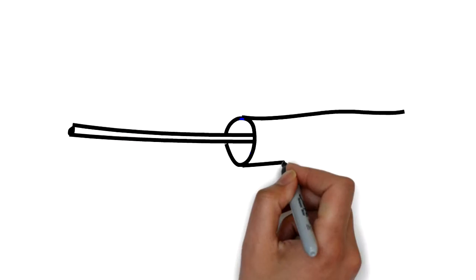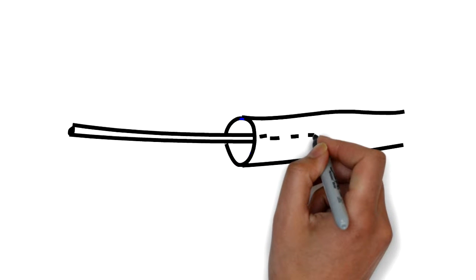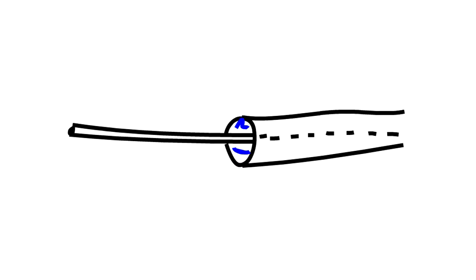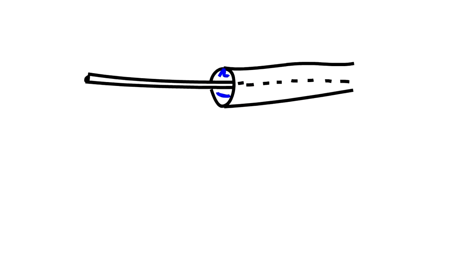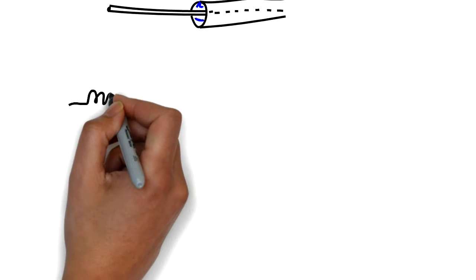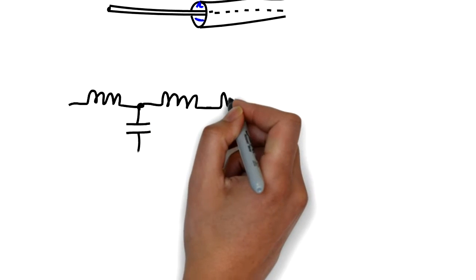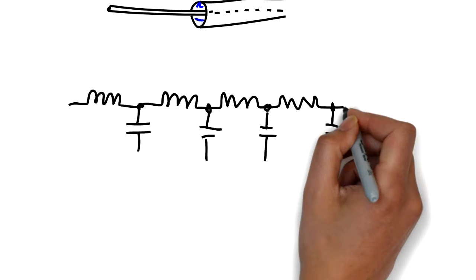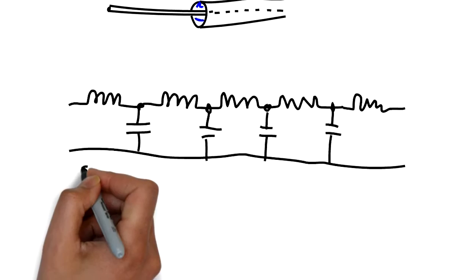Coax cables consist of a center wire conductor surrounded by a metal tubular conductor which are separated by an insulator. Having two conductors separated by an insulator reminds us of a capacitor. Watch our Back to Basics episode on capacitors if you need a refresher. We also know that every wire has inductance because it will establish a magnetic field around it when there is current flow. You might want to review our Back to Basics episode on inductance too. So a coax cable can be modeled as a wire, which is a sequence of inductors that also has capacitance with respect to the shield.